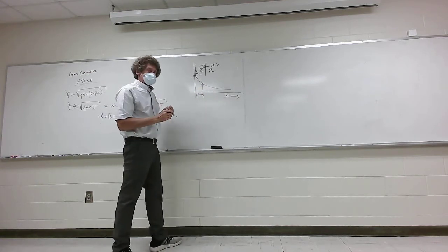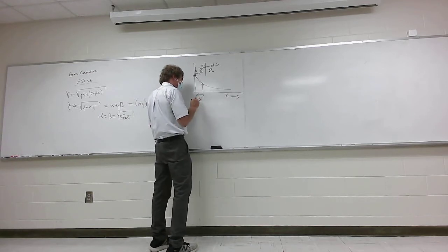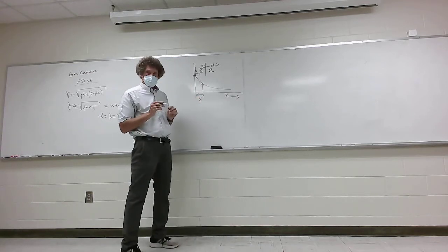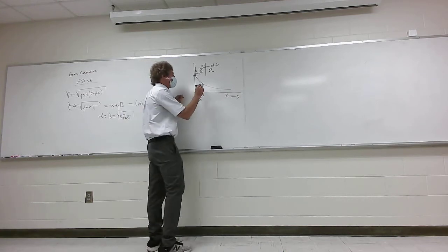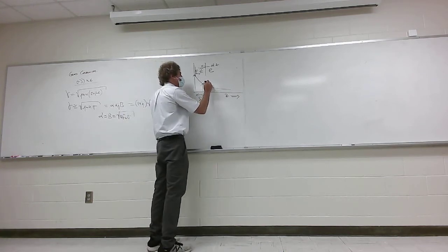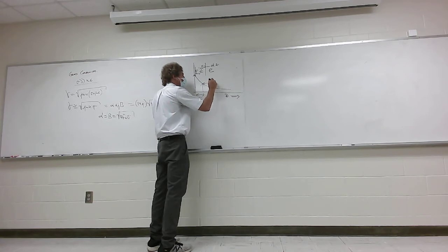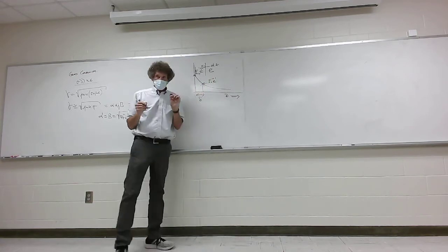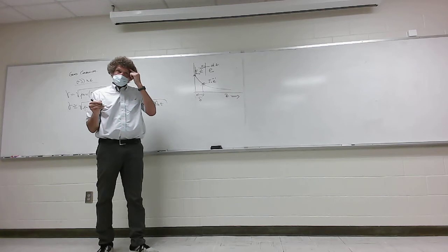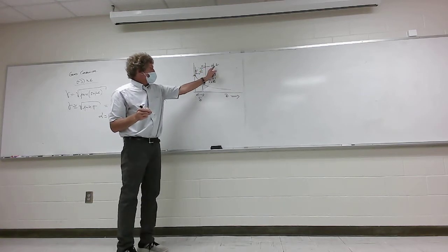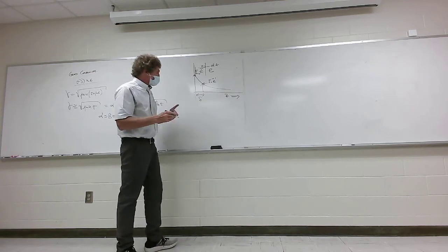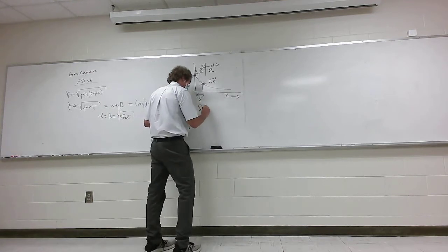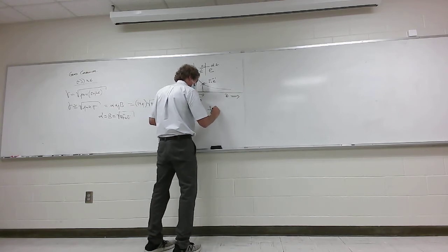where you're at what's called the skin depth. All right? That's the symbol for skin depth. Listen to me now. You don't have to write this down yet. This is the point where the electric field becomes E naught e to the minus 1. You follow me? And now in your mind, you know that means that alpha z equals 1, or alpha times the skin depth is 1, or the skin depth is equal to 1 over alpha. That's how they get it.